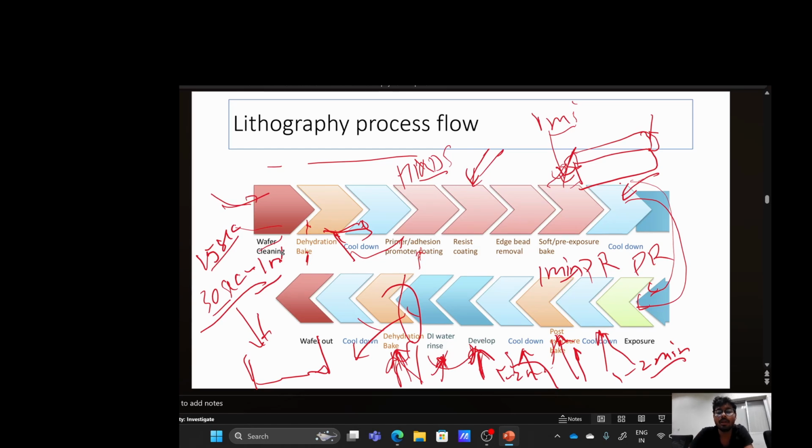So at this point you should check in the microscope. Otherwise, if you go directly to metallization, or the post processes like metal deposition, you will be wasting everything later on.